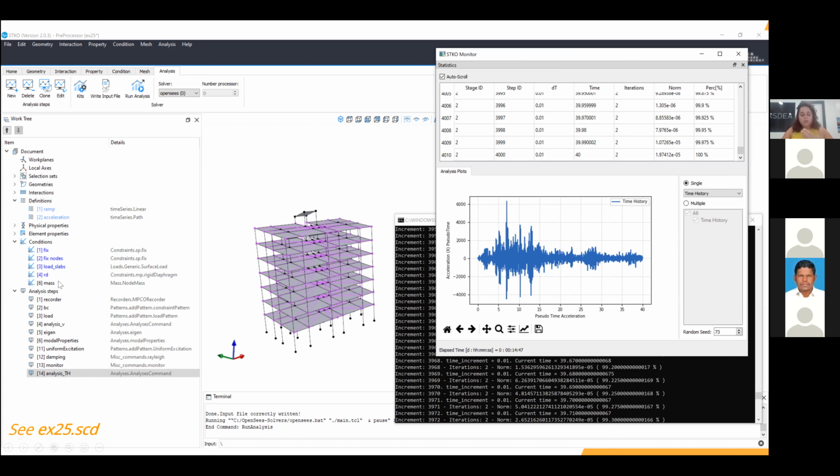I don't have the horizontal load from the pushover anymore, and I have mass defined at each node of the structure. So you can monitor, for example, the acceleration at the top level in reference to the time of the analysis, and see how this can follow the accelerogram that you have, and how the stiffness and rigidity of the structure can impact the response in terms of acceleration.